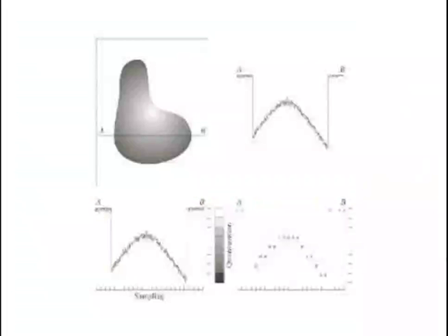The vertical tick mark indicates the specific value assigned to each of the 8 intensity intervals. The continuous intensity levels are quantized by assigning one of the 8 values to each sample. The assignment is made depending on the vertical proximity of a sample to a vertical tick mark.